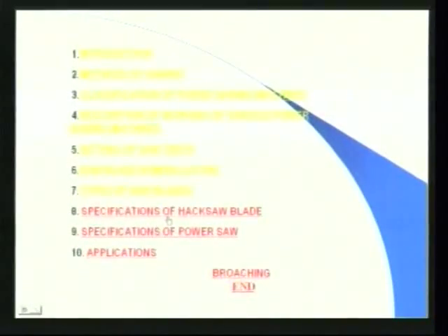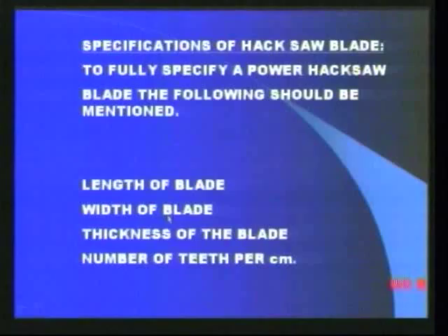Now we discuss about the specifications of hacksaw blade. In order to purchase a blade, we fully mention the specifications of the blade, the following specifications of the blade. One is length of the blade, next one is width of the blade, and next one is thickness of the blade, and next one is number of teeth per cm, that is called pitch of the blade.